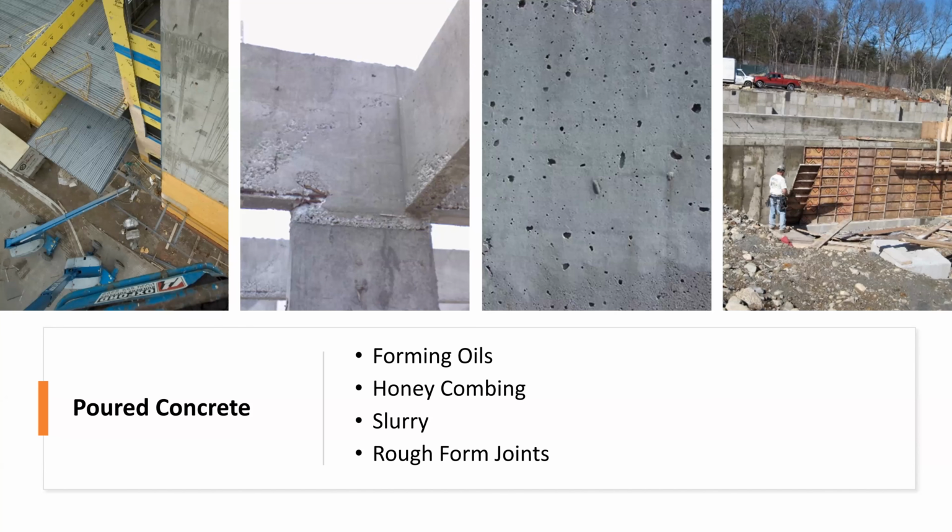When you look at the two middle pictures, we see some honeycombing and we see some holes, like we call them bug holes. Well, bug holes aren't necessarily a big deal if you're using a spray foam or a self-adhered membrane. They tend to be more of an issue if you're using a liquid applied membrane.